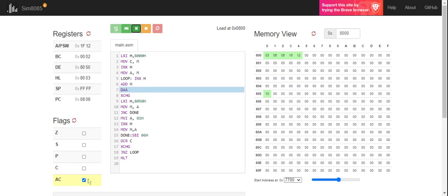How will it add 6? The auxiliary flag is already enabled over here. It is going to add the 6 and I've now got the 25. So 5 plus 5, 10, 10 plus 15 is 25. So I've got the 25 in this particular input over here. Now I hope you understand why I gave this SBI 06 over here. The auxiliary carry flag cannot be programmed by the 8085 programmer. So please remember that. Okay. So next, again I have to exchange the values.